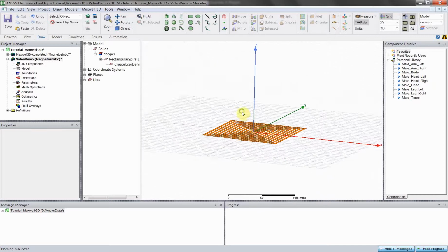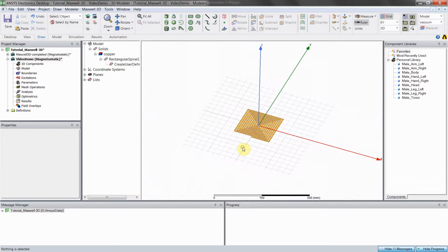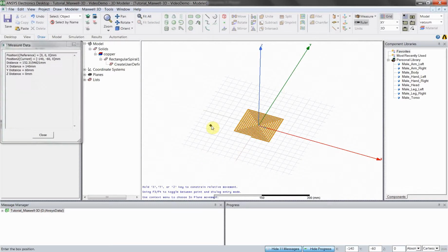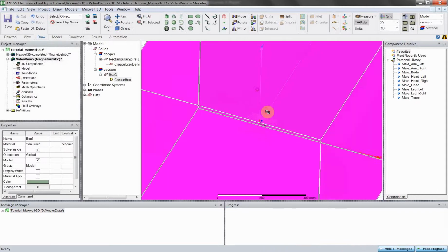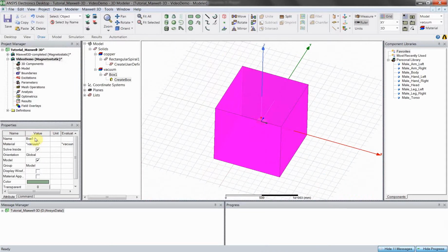We're wanting to create a region where our simulation is going to take place. So typically, what we're doing is a cubic meter region. So you tab into the bottom right, and you have your first point of your cube at -500 all around, and you make it 1,000 by 1,000 by 1,000 millimeters, so 1 cubic meter. Well, here's our region, and we can just name it region.